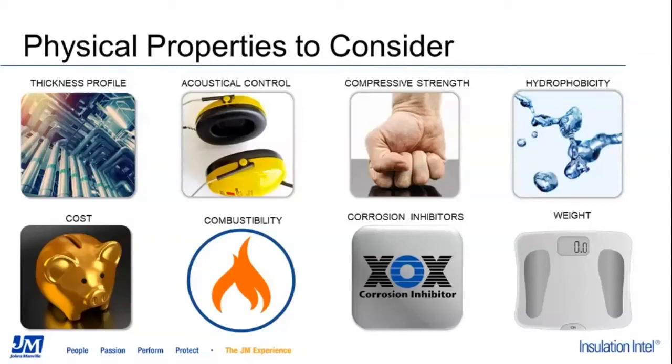Hydrophobicity, the capability of the insulation material to not absorb water, is becoming a very important factor these days as people are looking at corrosion under insulation and the ability of insulation materials to help slow down the rate of corrosion under insulation. In many projects, cost is a key element, so you'll need to keep that in account.